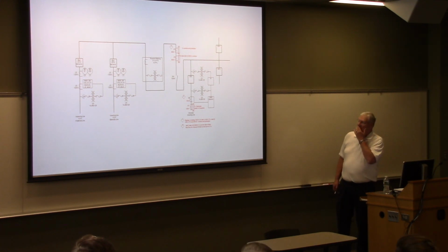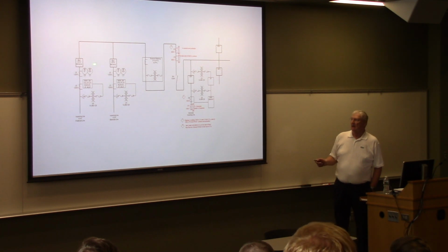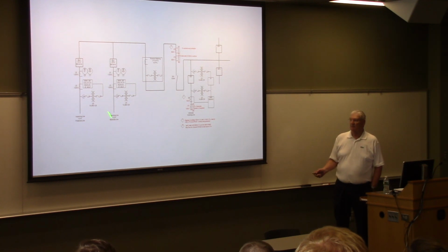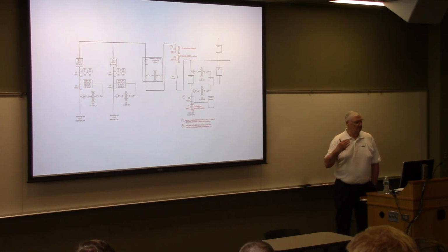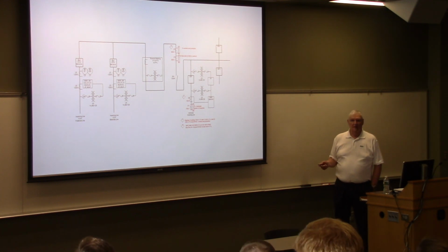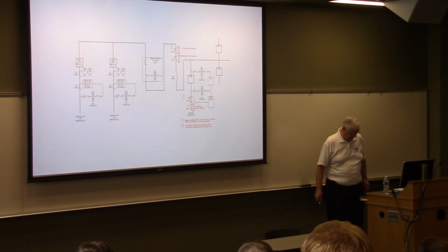This one is cute, it's unique. This comes from 2 different substations. And when they're going to switch from one substation to the other, they parallel these 2 feeds. They close both in breakers. The utility company does that. But there's no telling that both of those substations are at the same voltage or at the same reactive kVAR setting, or that you won't have a pretty significant swing of currents between the 2 of them in order to go through your transition. So I had never seen that done before in a customer switchgear, but they seemed to think it was okay, so anyway.